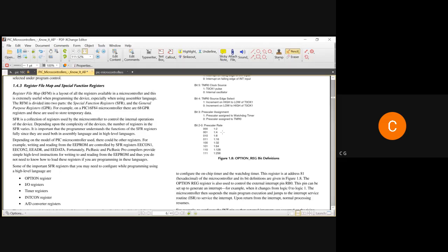Okay. So providing the extra time is done through a certain reset switch, and this is done by the prescaler. It keeps monitoring the timing, and it knows that the watchdog timer is about to reset the machine. Before that, the watchdog timer is reset itself, so it extends that time by another machine cycle.